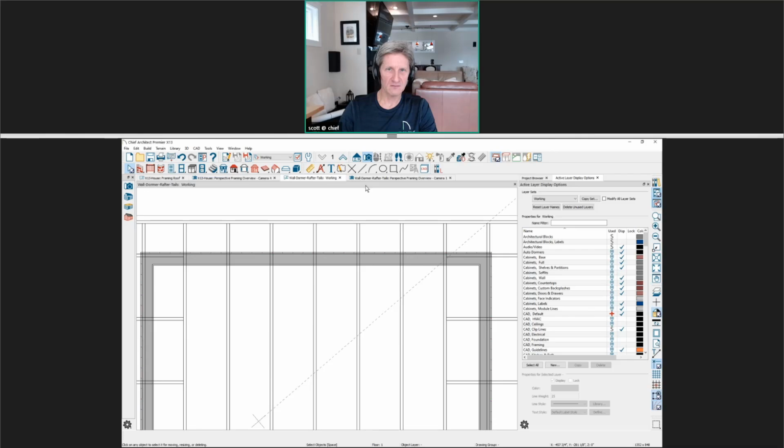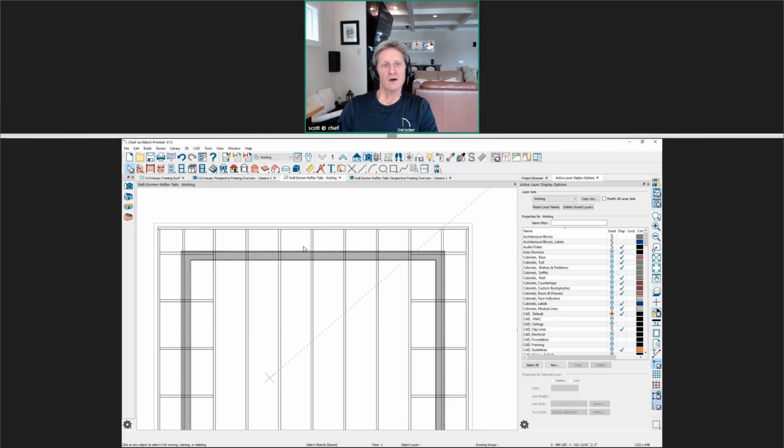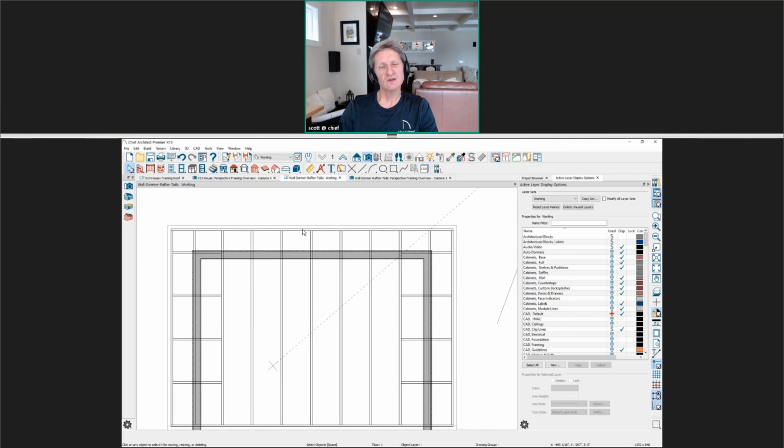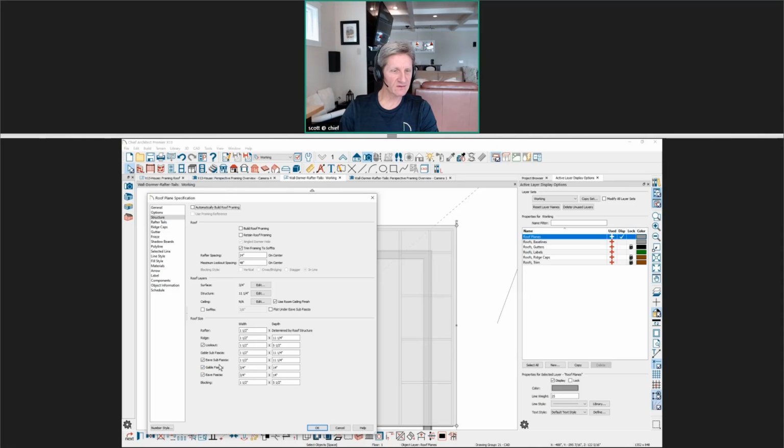But you can't do that for the gable end, Larry. Here's your gable color. You would just have a single barge rafter instead of a sub-fascia. So you want to control it for the gable end as well. So let's remove that fascia back off of there, and let's just uncheck gable fascia. The gable subfascia doesn't have a selection box, right, but I think you could zero that out. You want to remove it? Yeah, so you just have the one member, your ending barge trim.